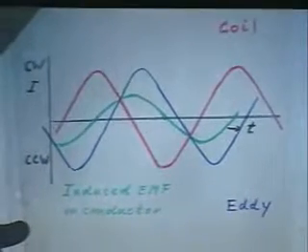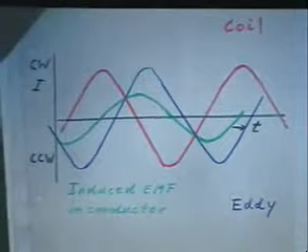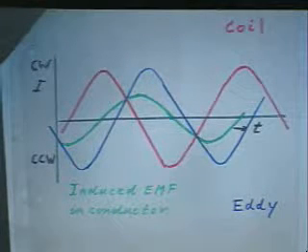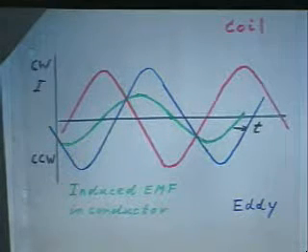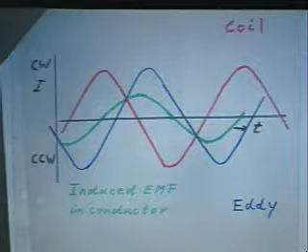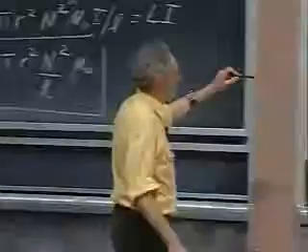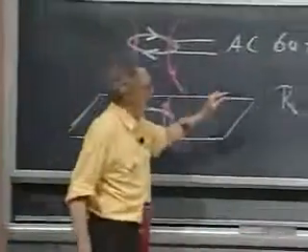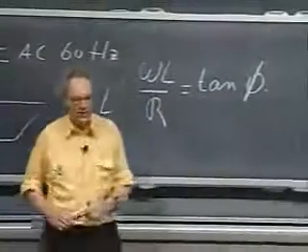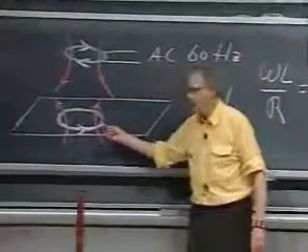But the net result is, even though the shift is not 90 degrees, that you get on average a repelling force. And so the secret of the repelling force in the case of the levitation of this coil, and therefore of the levitation of the woman, lies in the fact that there is a finite self-inductance in here.